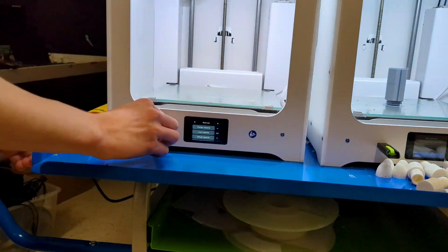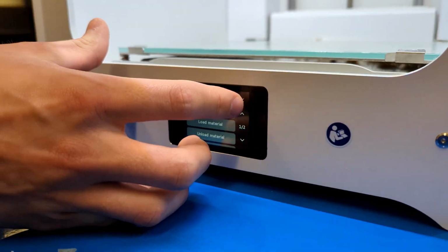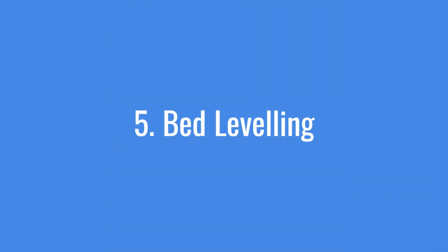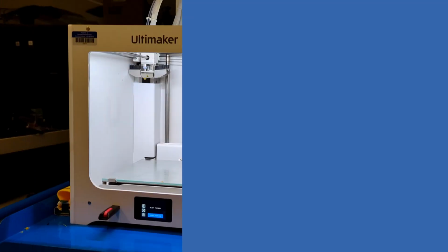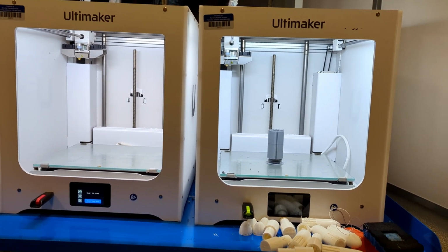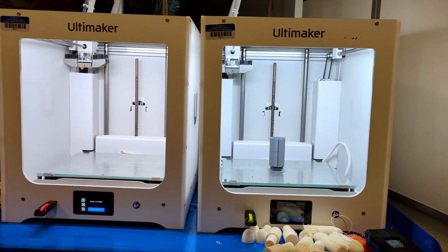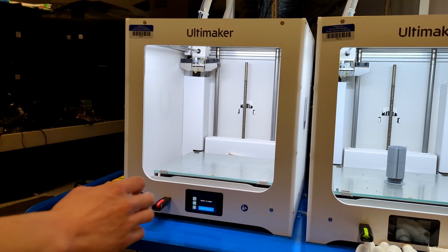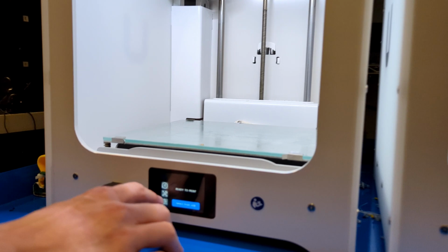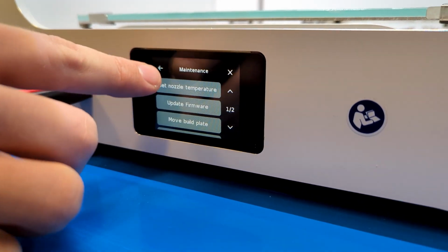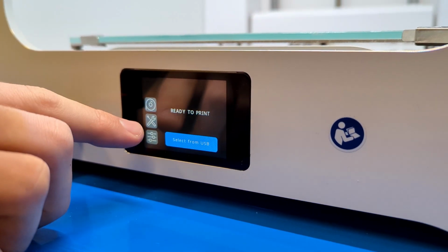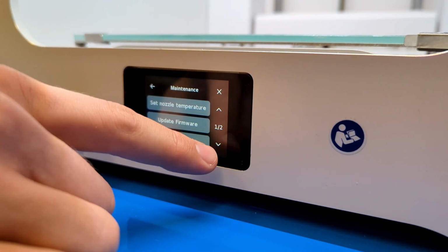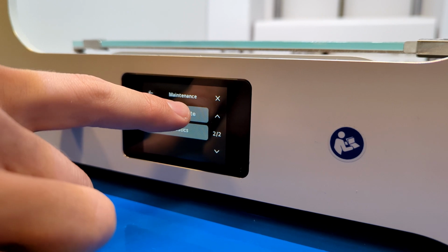So you put it in the printer, and then the next step is to level the bed, because we aren't sure if it's level. If it's already level, or you know it's been leveled recently, you can skip this step, but generally it's good practice because you don't really know when the last person leveled it. So to level the bed, you click the little, I'll go back to show you that, the little screwdriver and wrench, that's like the maintenance tool. Then you can say level build plate.